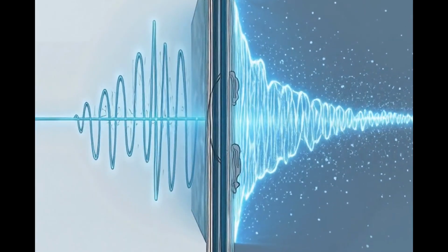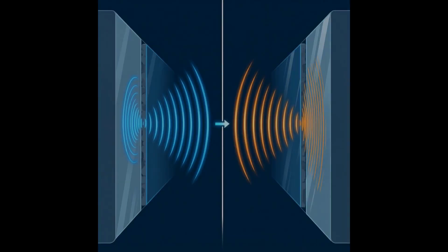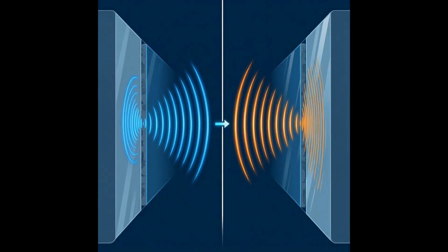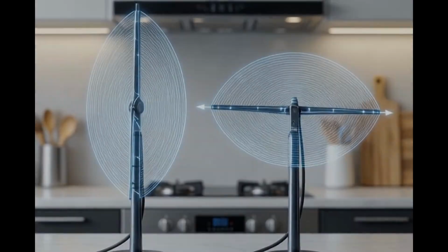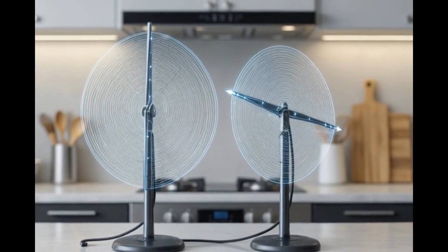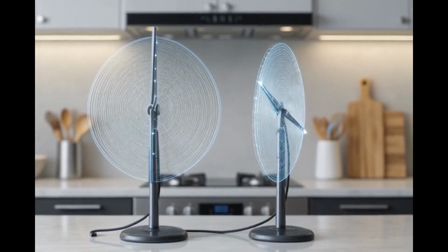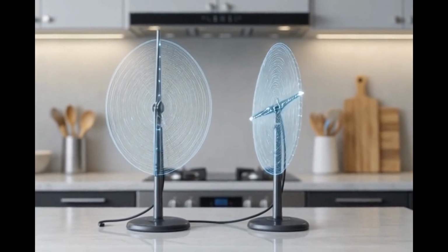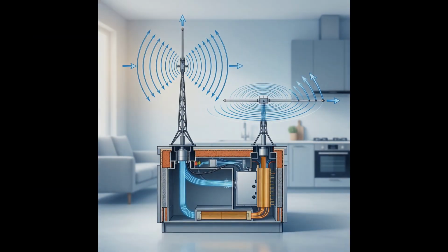The geometry of your kitchen affects signal strength not just through walls, but also through antenna alignment. Every radio wave carries a specific polarization direction determined by the transmitting antenna's physical orientation. Maximum power transfer occurs only when receiving antennas match this polarization vector field precisely.